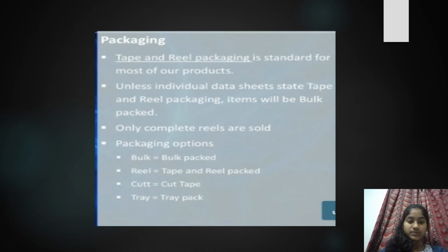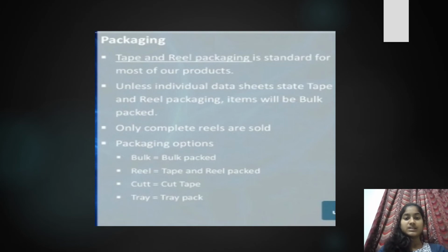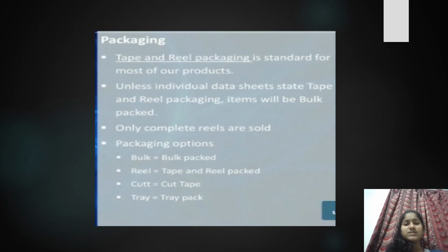And the output. Transfer function or slope polarity. Although it is more normal for there to be an increase in frequency for an increased input control voltage, this is not necessarily always the case. When selecting these electronic components, it is always necessary to check the polarity of the slope. A positive slope means a positive change in voltage will cause the frequency of the VCXO to move higher, while a negative slope means a negative change in voltage will cause the frequency to move higher.